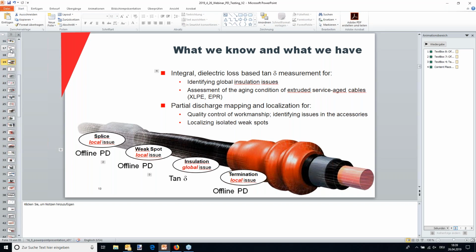So Robert, this is a good opportunity. This questioner asked, what is the IEEE or any other standard for this test? Does the standard specify the PD value for service cable and new cable, service stage versus new? I know we talk about IEC often, but given most of the audience is IEEE, it's a good opportunity to make this clarification. In IEEE, there is a separate chapter on that, which is IEEE 400.4 for the damped AC. And IEEE has not established absolute values yet.